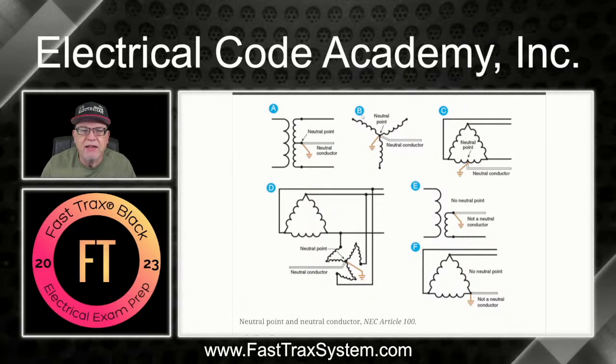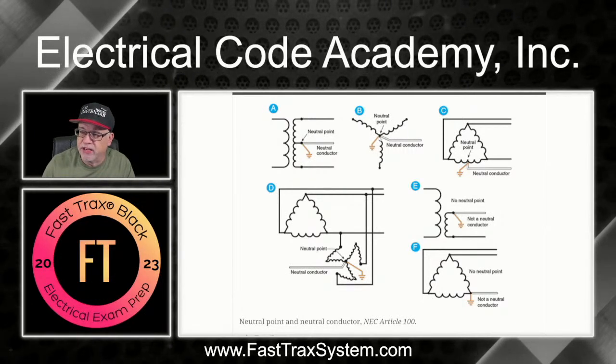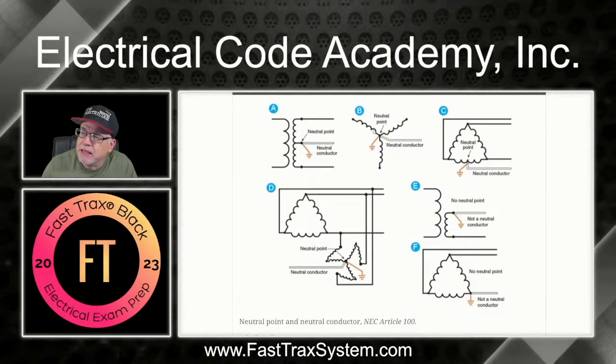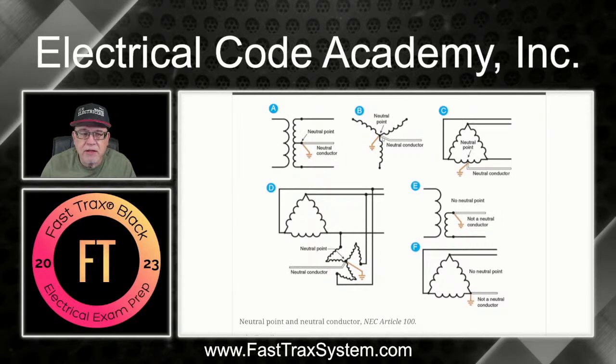All right, this is B. Now this is that example of this 4-wire, 3-phase Y configuration. Here's the center point, or the common point, right? So in this case, if this was a 208/120 volt system, then from here to here, it would be 208, right? But from here to here would be 120. This is the common zero reference point because this is connected to Earth. And so this is where you're going to get voltage stabilization. And this is where the neutral is created, right here, okay?